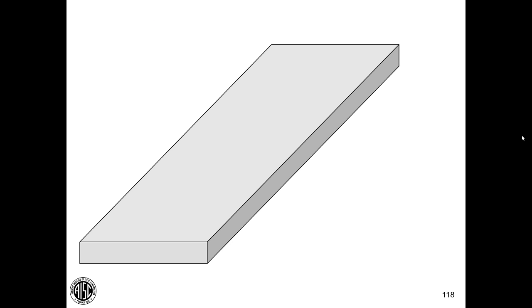You might have been taught at school that steel is isotropic, but we actually know it's anisotropic. It is not the same in every direction. Now, it's pretty good. And compared to other materials, the properties may actually look isotropic. But in fact, we have some differences depending on the orientation of our test specimens.